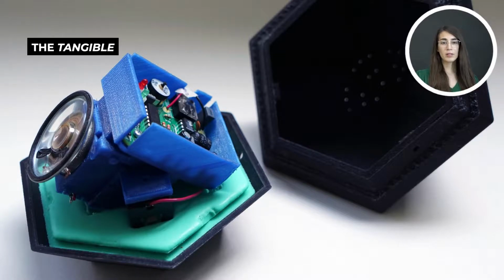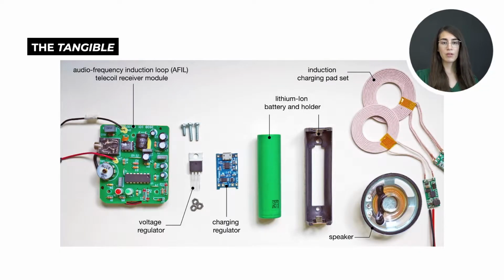One way of experiencing the soundscape is through the tangible, a handheld receiver device. Its components are mainly parts of an off-the-shelf telecoil receiver module. We removed the casing of the receiver module and replaced the battery supply with a rechargeable battery system consisting of an induction pad set. A charging regulator module and a voltage regulator control the charging and the voltage. A small speaker is used to sonify the electromagnetic field signals.